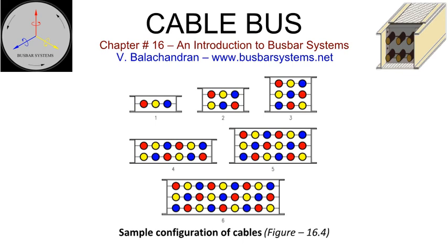For outdoor transformer termination within a cable end box, it is preferable to adopt a horizontal entry for better weather protection. Tap-off boxes. A tap-off connection facilitates diversion of part or whole of the power from the main connection to another branch. It comprises an enclosure with rigid bus bars supported on porcelain or epoxy insulators with rated current and basic insulation level, compatible with that of the cable bus, and shall have a minimum degree of protection of IP55.